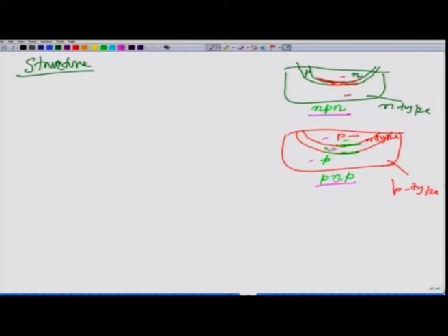So, this is how it is made, and schematically, if I take this kind of a cross section, I can show it as we did for the PN junction. You have a junction here and you have a junction here, and let us say this is Npn. So, this is N, this is P, and this is N, and you have a depletion layer. The same physics will go: you have a depletion layer here and a depletion layer here, the same things. You have charges, but no charge carriers in the depletion layer. Remember all these things?